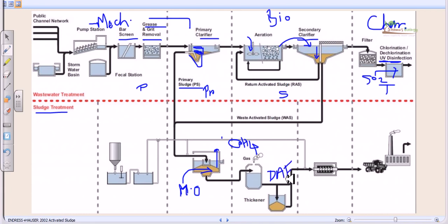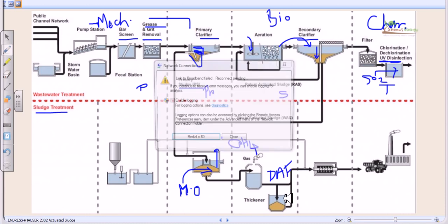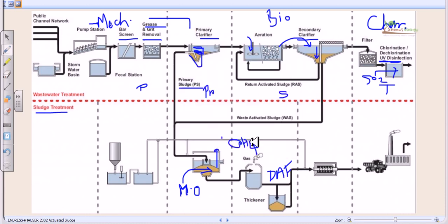Now this type of sludge thickener, what it does is, inside a huge chamber, they push air onto the sludge at very high pressure, and then just release the pressure so that the sludge will float to the top and the watery part remains at the bottom. As a result of this process, we can have really solid and thick sludge.